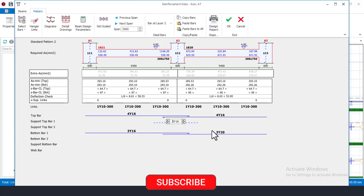Then I'll come at this button now. Okay, let me just give it the top here. Now you can see how I have now arranged this bar. That means that the first layer is going to carry 4Y16 all through at the top, and that is T1, and then the T2 right now, which is the second layer, will be carrying only 3Y16 only at this support here.